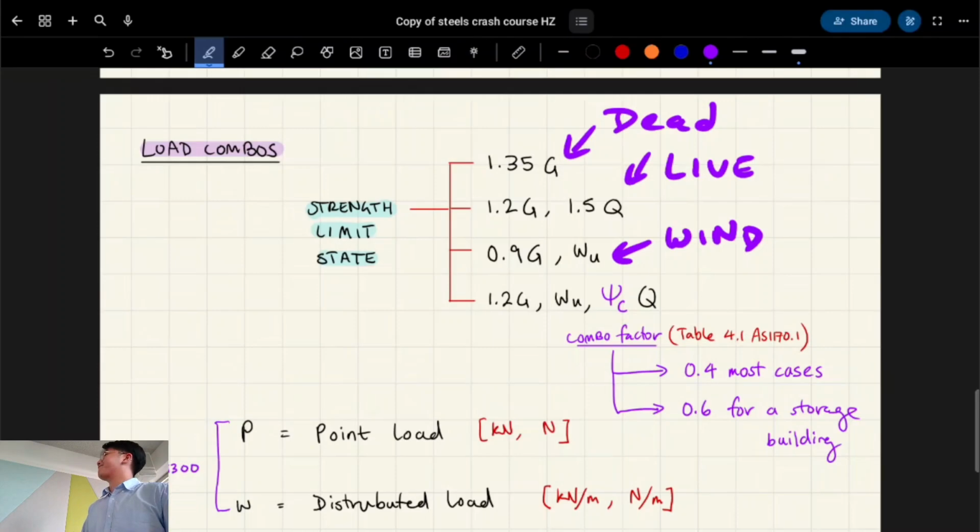Just an example, right? That column there, for example, acting on this floor, is that a dead or a live load, would you say? It's a dead load, right? So why is it a dead load, you reckon? Yeah, unless they renovate the building finally. What about this whiteboard? Is this a dead or a live load? Live, exactly, because I can just move it, right? Humans, live loads. These tables, they're movable, live loads.